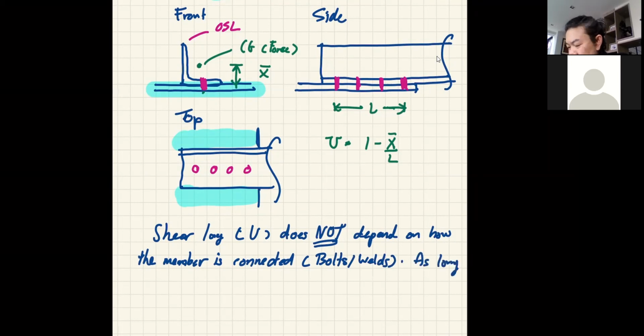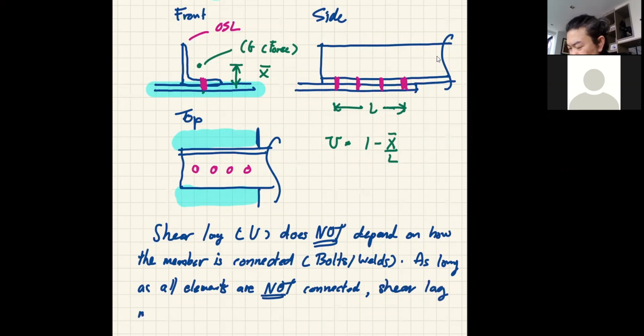As long as all elements are not connected, shear lag must be considered. Okay, so that means if I don't use bolts for this one, if I instead weld this, I still have shear lag problem.